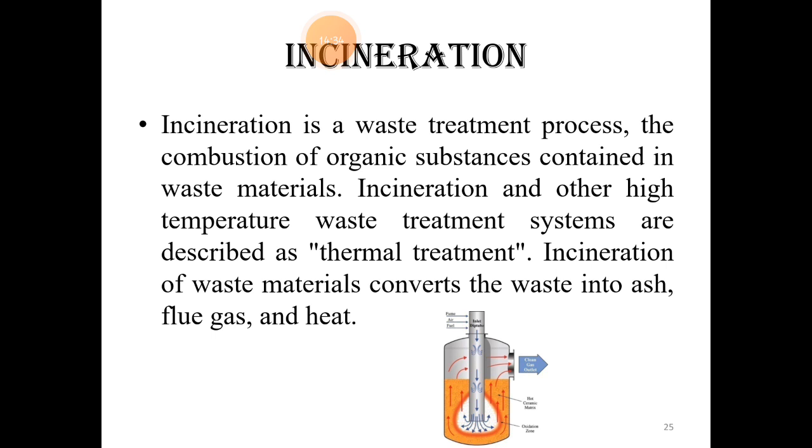The next method of disposal is incineration. Incineration is a waste treatment process wherein the combustion or burning of organic waste materials is done in a closed system. Hence, it is also called a thermal treatment process. Here, the waste materials are converted into ashes, gases, or even into heat energy. Down the slide, here is a picture of an incinerator system.